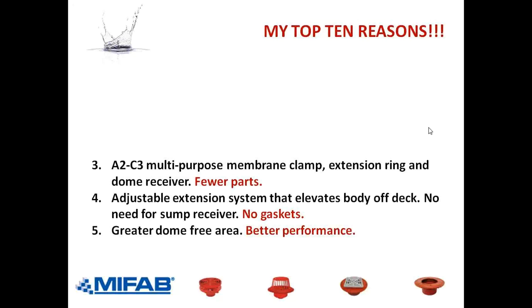Number 4, we have this adjustable extension system that we saw photos of, and that elevates the body off the deck using a bearing pan turned upside down, using an A368-DC deck clamp on top of the pan, then the HS3 hardware to hold the body off the deck. Fewer parts, no gaskets. And then the A2C3, the multi-purpose ring to receive the dome under deck clamp if you need it, and the extension ring.